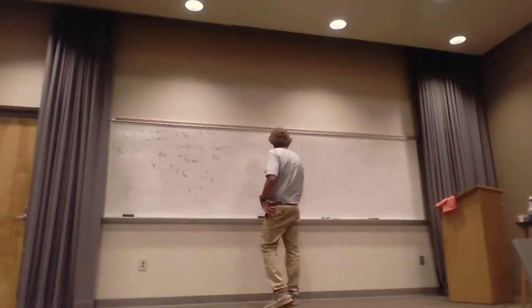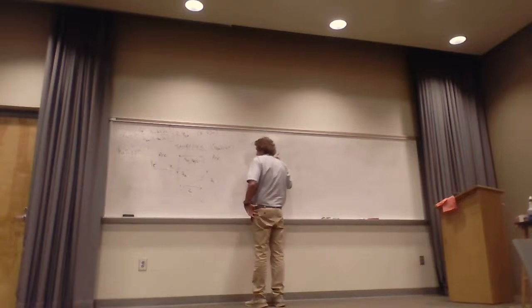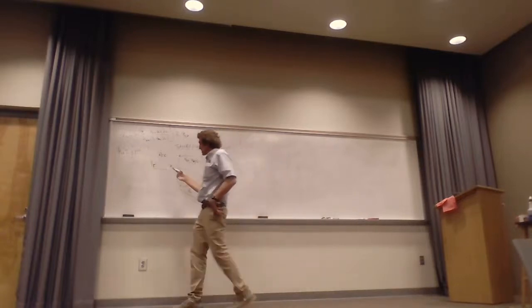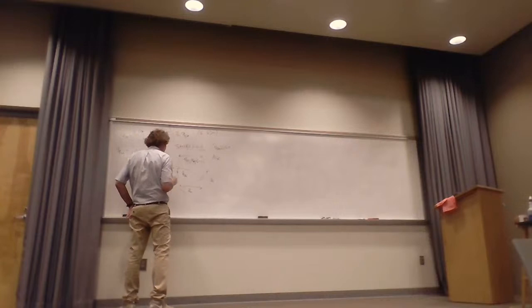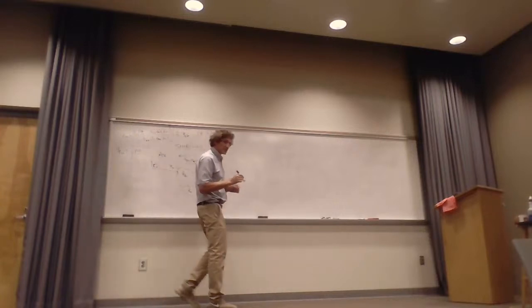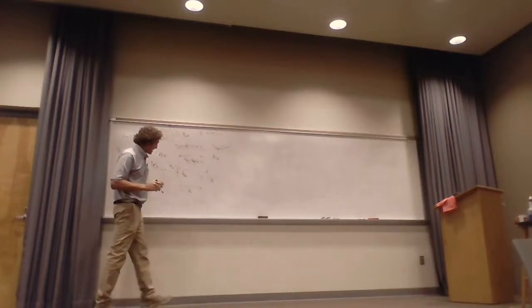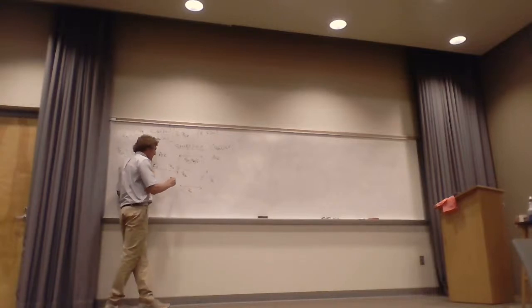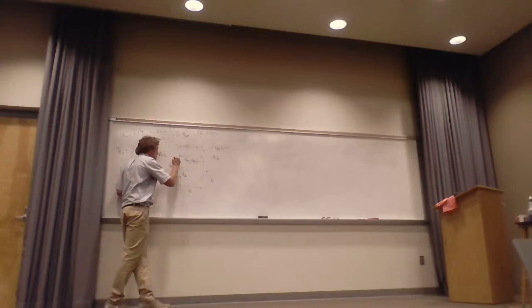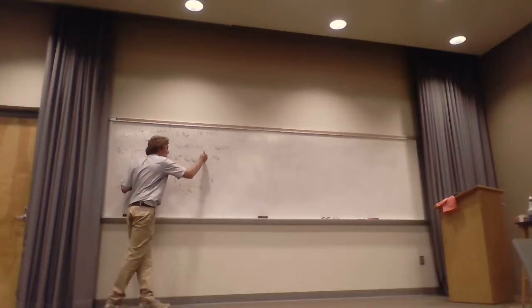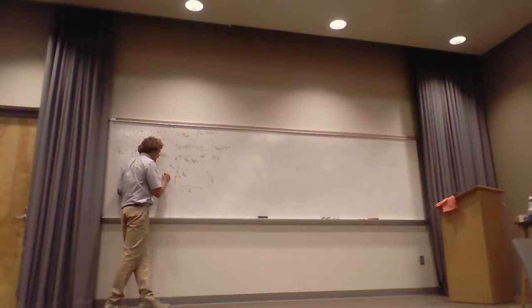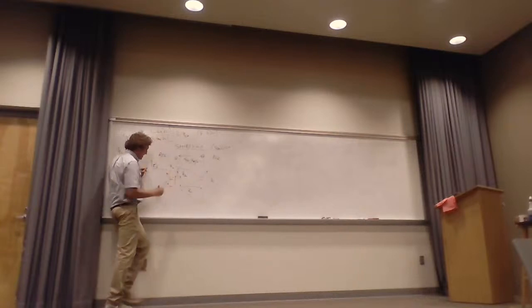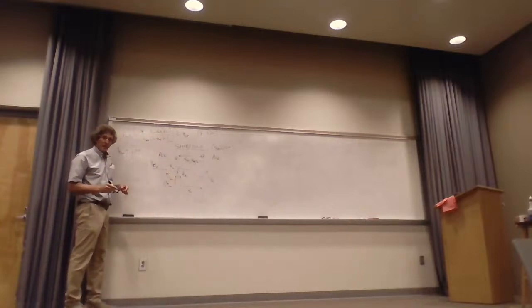So now we can say that the actual, if I take an electric field here, that's the incident electric field, and let's assume I know eta of the shield. Now there's two things I have to concern myself with. First, I need the transmission coefficient right here. Call this boundary 1 and this boundary 2. So I need the transmission coefficient there. I don't have to, but I can get the transmission or the reflection coefficient there. You with me on that?